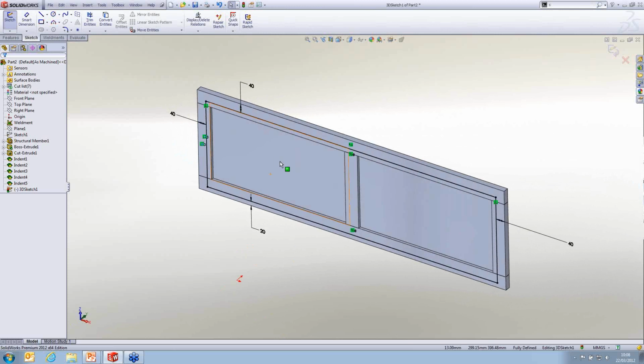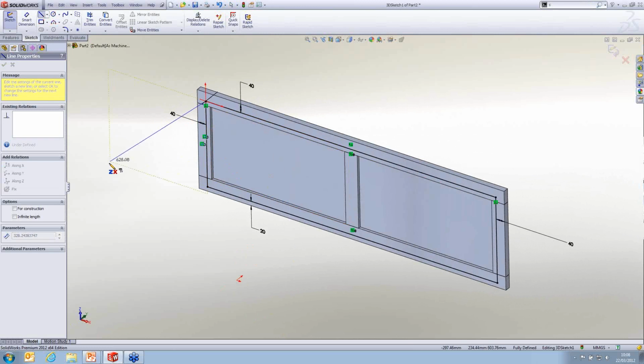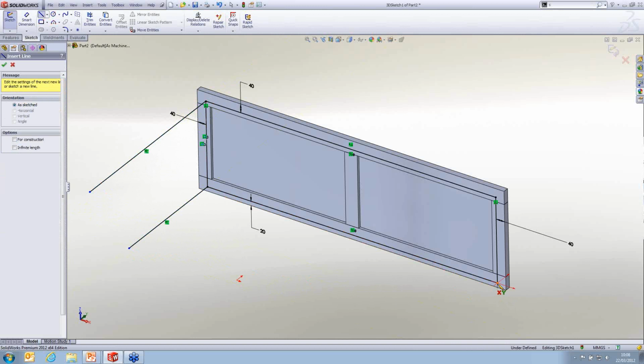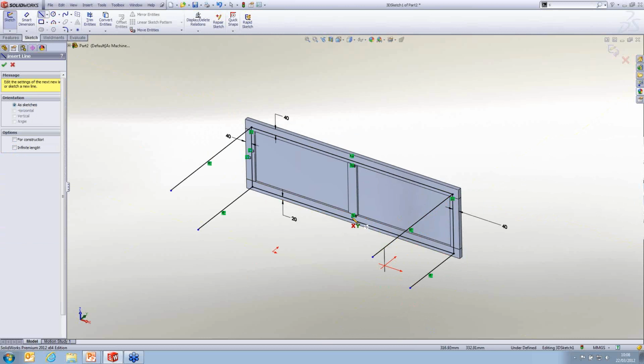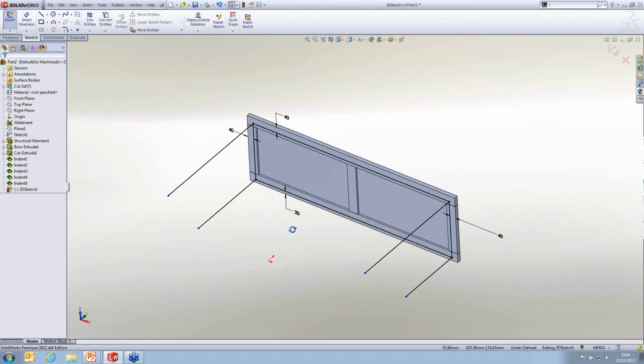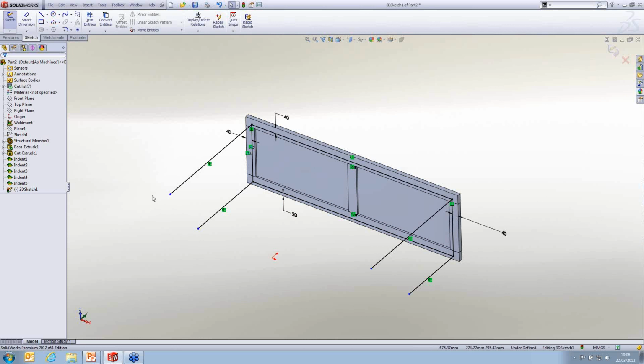So the next thing we need to do is draw out where our legs are going to be. Again, you'll see here we're in the ZX plane. Clicking tab will adjust us to the XY, which is where we want to be, and I can draw out my 4 legs like so. If you maintain that yellow line as a snap, it will create that relationship of along Y for you automatically.